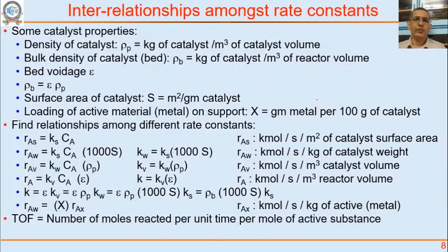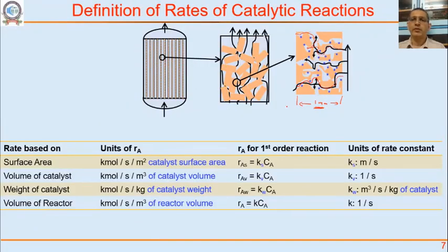And porosity is how much, so if I take this as, let's say, the surface of the catalyst, what is the area occupied by pores? So if the catalyst is, let's say, 1 millimeter by 1 millimeter cross section, the ratio of the area of the pores to the area of the cross section of the catalyst is called porosity. So we want porosity to be as high as possible.